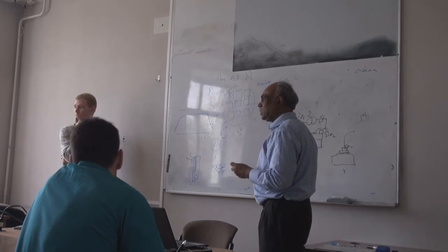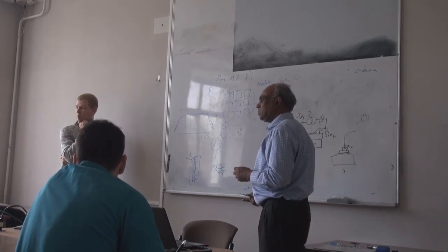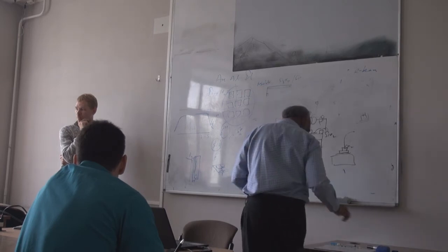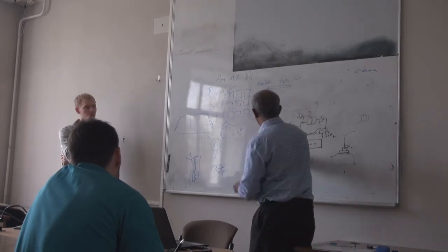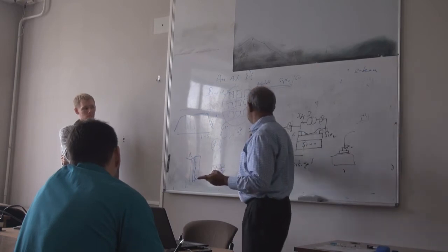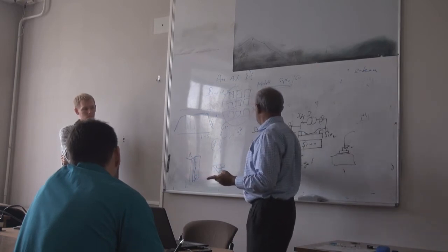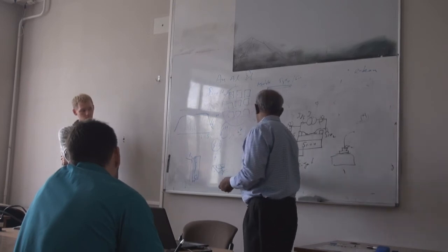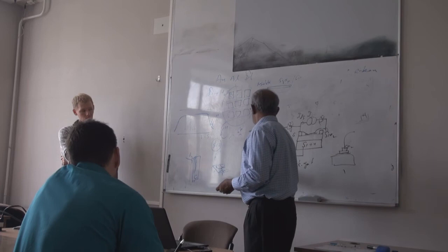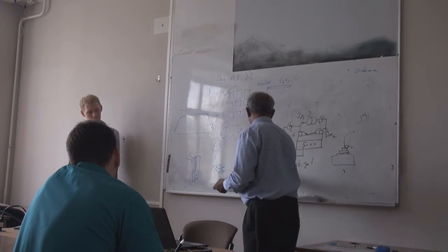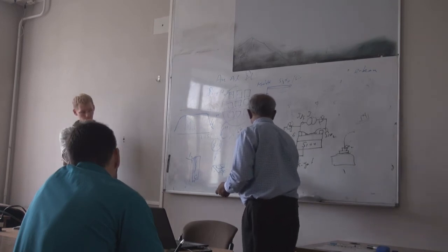Please tell me about the conductivity. Carbon nanotubes, the important thing is they have two kinds: one is semiconducting, one is metallic. Semiconducting we can easily look at if I vary the gate voltage and measure IDS.